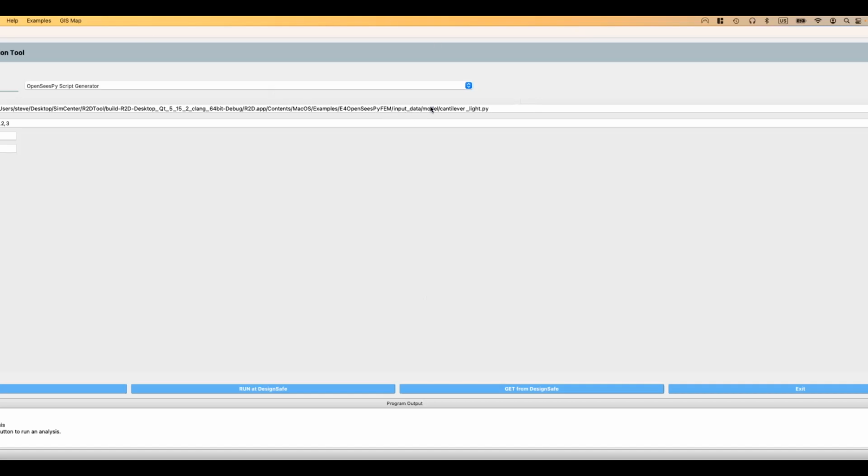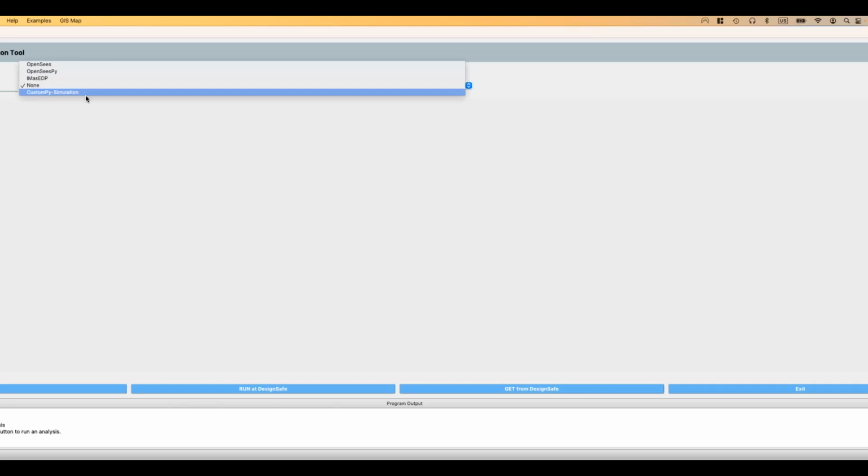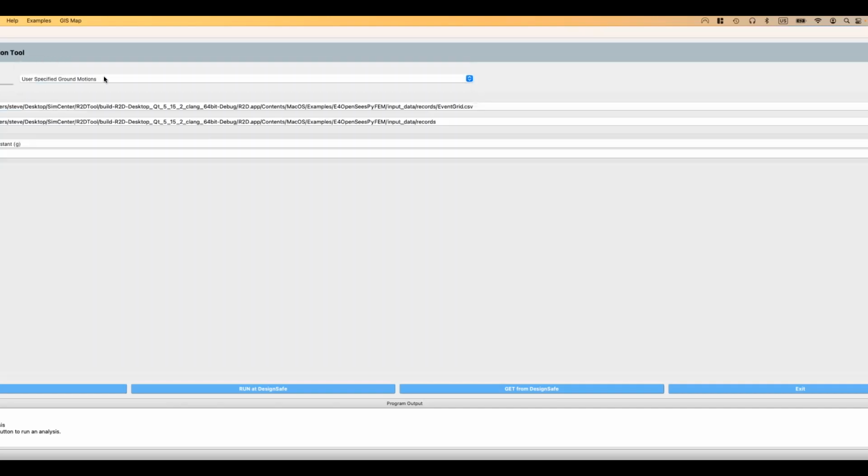So currently we support OpenSees and OpenSeesPy. I'm not sure if there's other types of analysis. If you do, for example, that electrical grid model, you can make your own fragility curves and implement them here. Can you also change or implement your own intensity measurements with those fragility curves, or how does it work in this? Yeah, so your intensity measures are supplied through your hazard definition, right? Your intensity measure field. And that is available downstream.